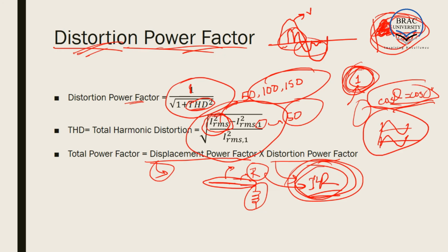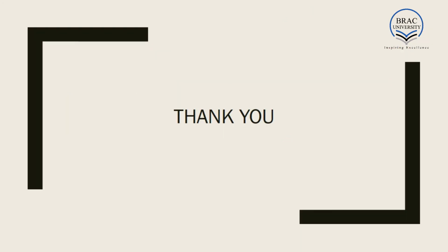And when we are considering a rectifier circuit which is converting AC to DC, it is driving a non-linear load, because input is AC and output is DC. In case of a non-linear load, we cannot just consider the displacement power factor. We have to keep the distortion power factor in mind, and we have to design our circuits accordingly. That's all for AC/DC rectifiers.